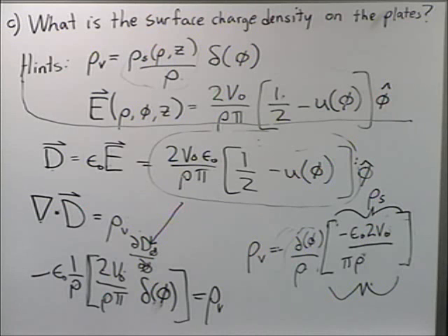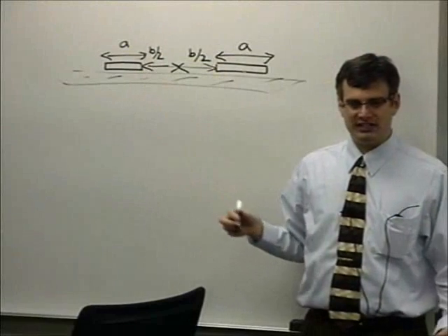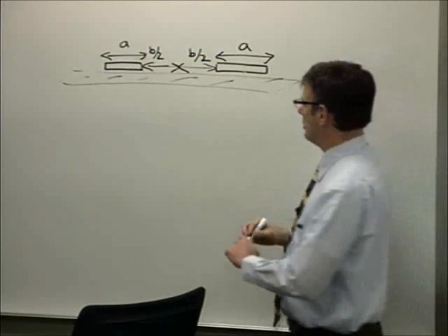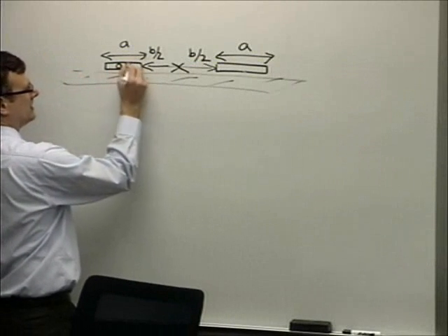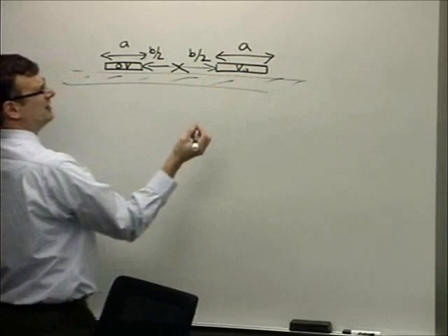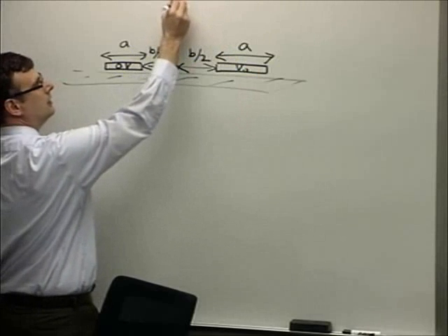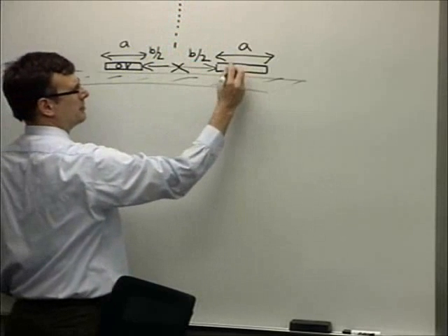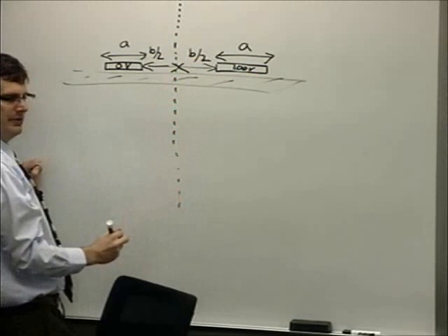Okay, let's take a look. We had one bright fellow point out that, hey, you could use this for this kind of problem, right? It's not a semi-infinite plane, but if these are pretty close together, then I could use this similar field solution to solve for it. If I wanted to draw the equipotential lines, for example, let's say this was at 0 volts and this was at V0 volts. Well, in our problem, let's say this was 100 volts. Let's put some numbers on this. So this is 100 volts. A 50-volt equipotential line would go right through the middle there.